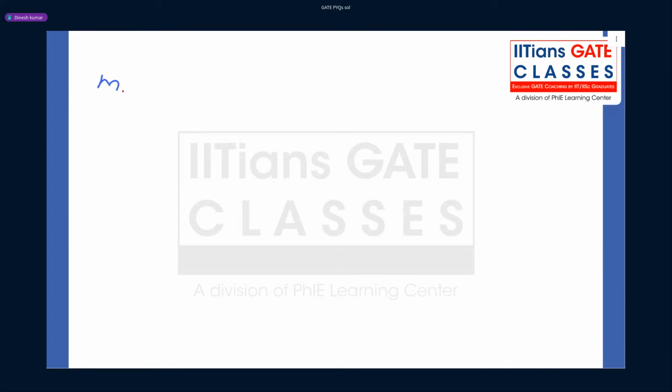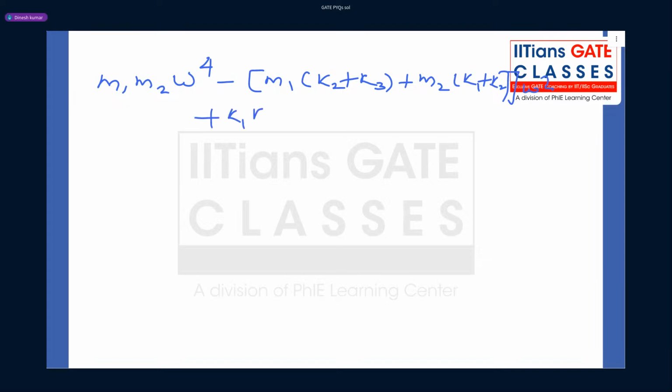It is given by what? m1 into m2 omega power 4 minus m1 into k2 plus k3, then m2 into k1 plus k2. This is multiplied by what? The whole equation multiplied by omega square, then k1 k2 plus k2 k3 plus k3 k1 equal to 0. This is the frequency equation for a 2 degrees of freedom system.